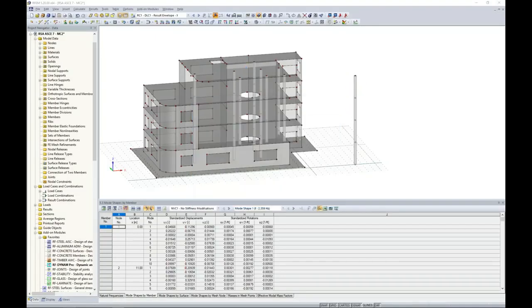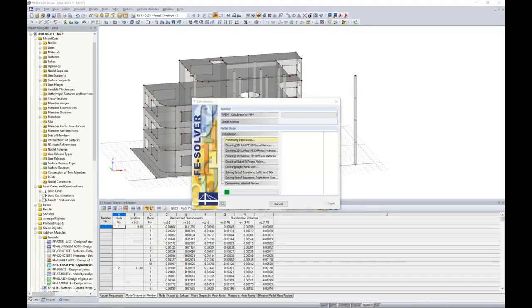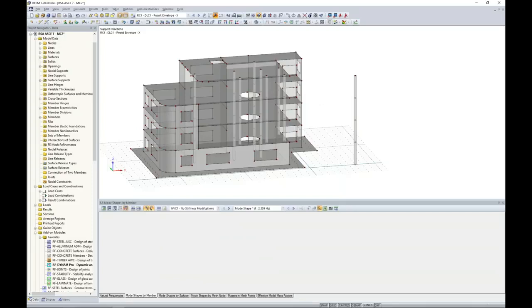Now remember, this column has absolutely nothing to do with the analysis, so it's not contributing any stiffness. Rather, we're just taking all of those mode shapes which are applied in the X direction and combining them per the CQC rule for this result combination. So eventually, the program will present to us our results here.